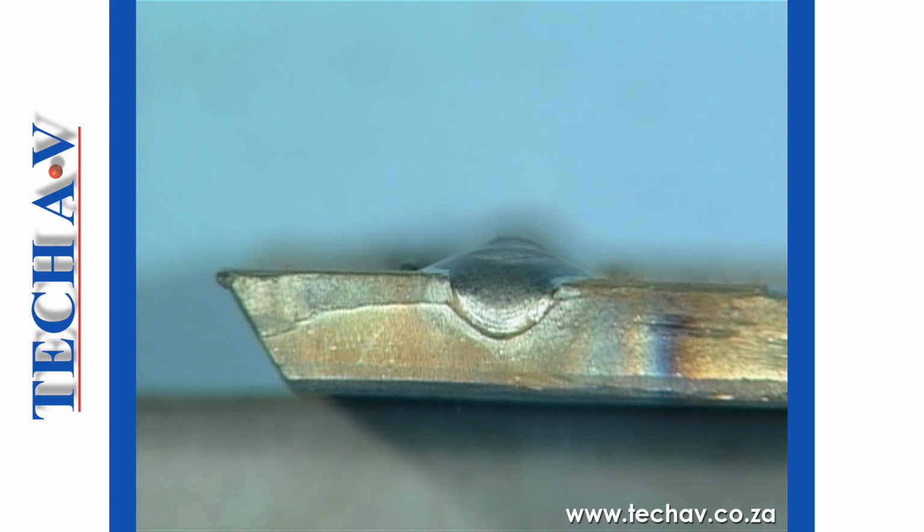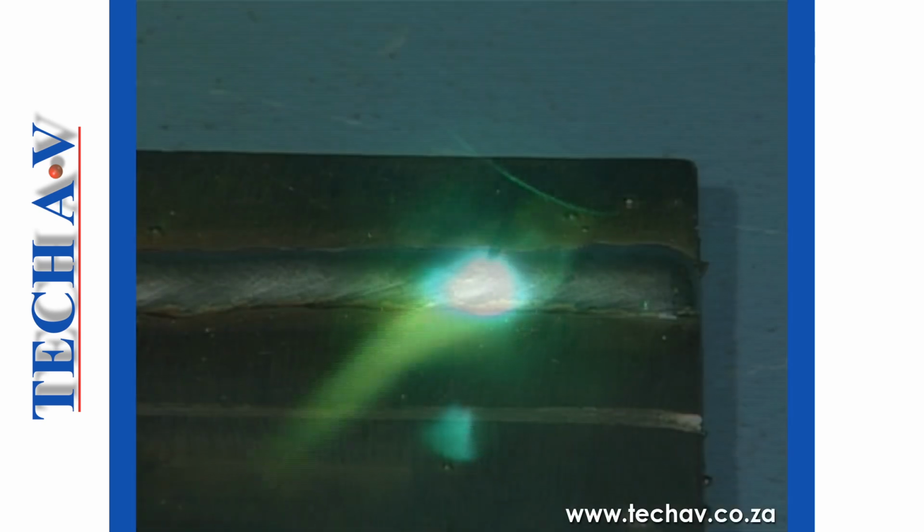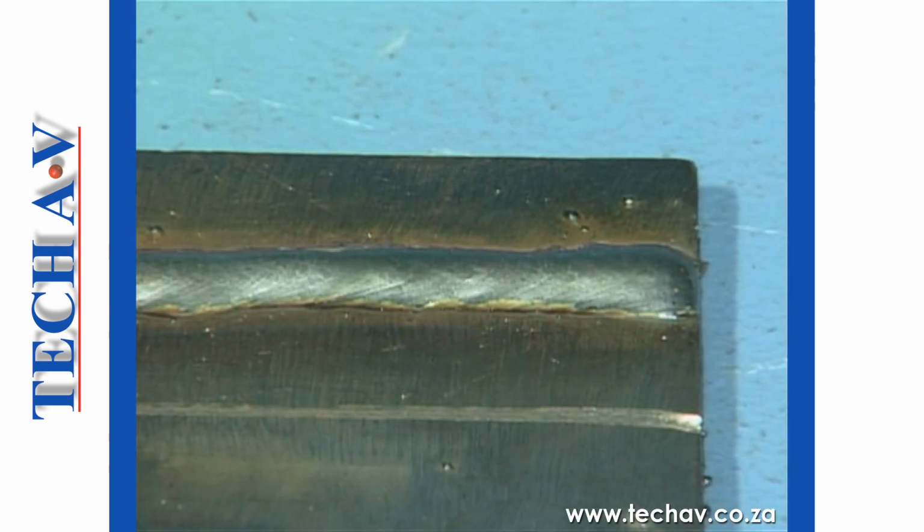Spray transfer is a hot weld, resulting in deep penetration, and for this reason it is used to weld thick material, but is limited in most cases to downhand position work. The result of spray transfer is a very fluid weld pool that freezes into a smooth bead.